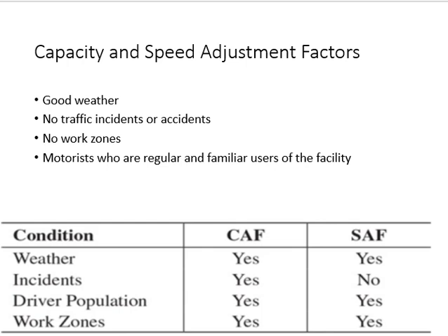What is the work zone? Any construction or maintenance activity happening on the road or close to the road. If it is on the shoulder or on the sidewalk, it's still considered as a work zone, because it's too close. Then the last condition is about the motorists or the drivers: all drivers are familiar or regular users. These are considered ideal. If you do not meet any of these ideal conditions, an adjustment would be required.